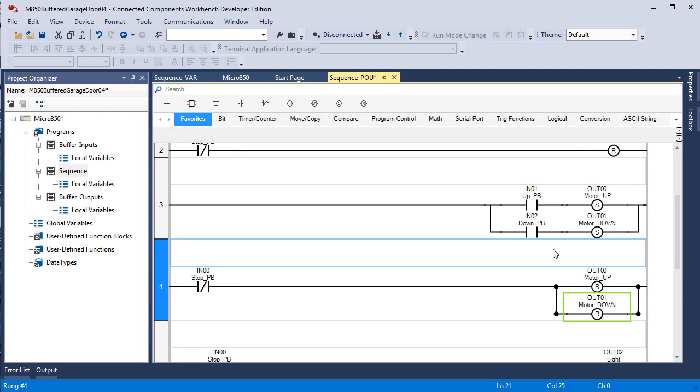We do have to have logic that prevents setting both bits. So here's a thought. Do we change the logic so if they push the opposite direction that it stops and then they have to push it in the right direction? In other words, if it's going up and they push down, do we just let it reverse, or do we want that to make it stop entirely and then they have to push the down again?